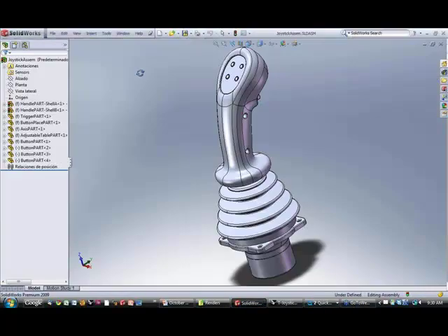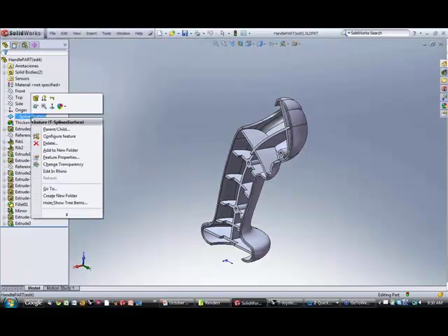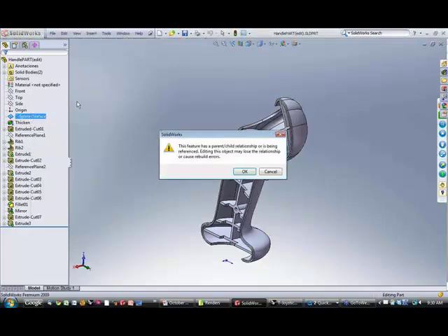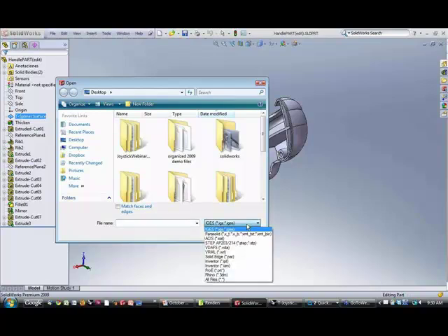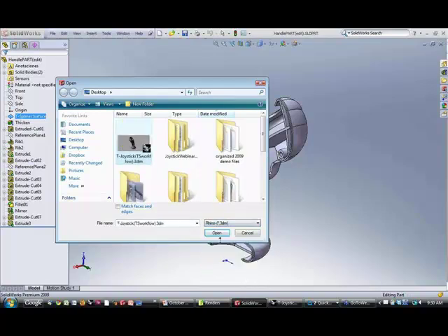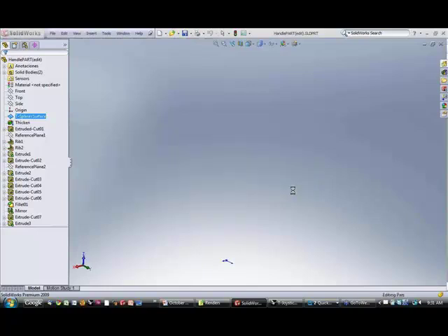And then back here in SolidWorks, we'll go back to our T-spline model. And here at this step in the feature tree where we've imported the T-spline surface, I can just edit this feature and load in the new T-Splines file. Now this will take a few seconds as it's recomputing and trying to rebuild the feature tree.